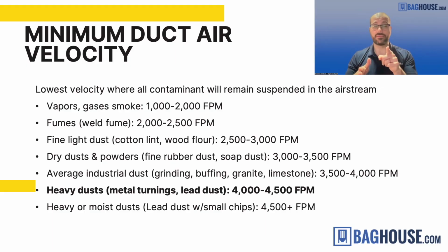Because we're going to use 4,500 feet per minute as our minimum velocity we want to maintain. Now when we look at our chart, we see 4-inch, okay, that's this speed. A 4-inch pipe with 4,500 feet per minute is 395 CFM. And then I have a 6, okay, a 6 is 888 CFM. And then with that, we simply count and add up all the sums, and then we get our final ductwork sizing, our total airflow requirement for the system.